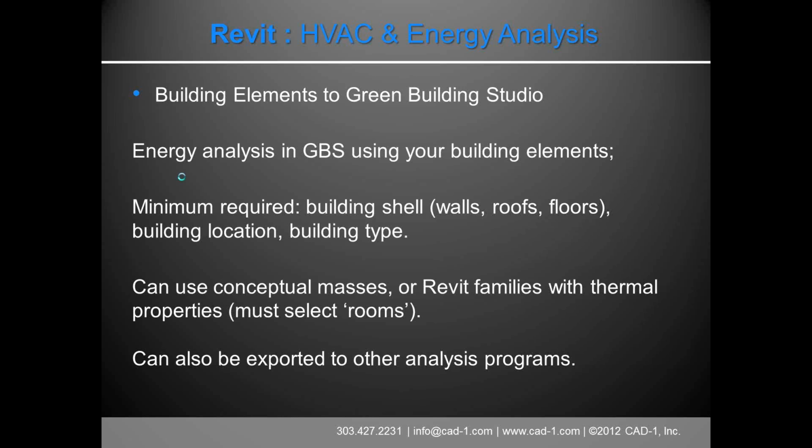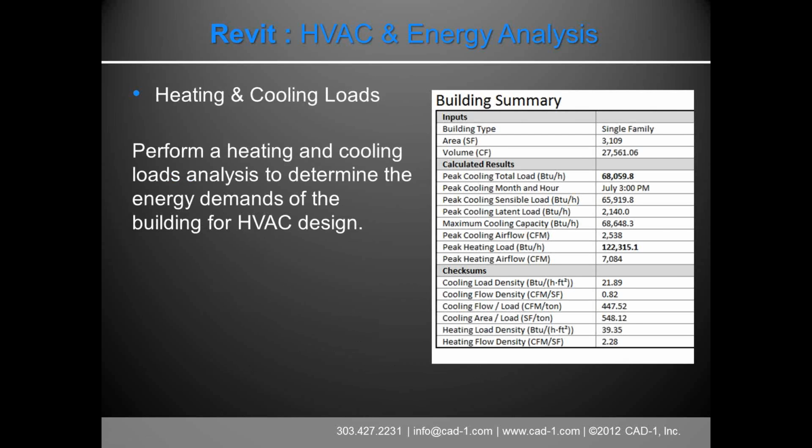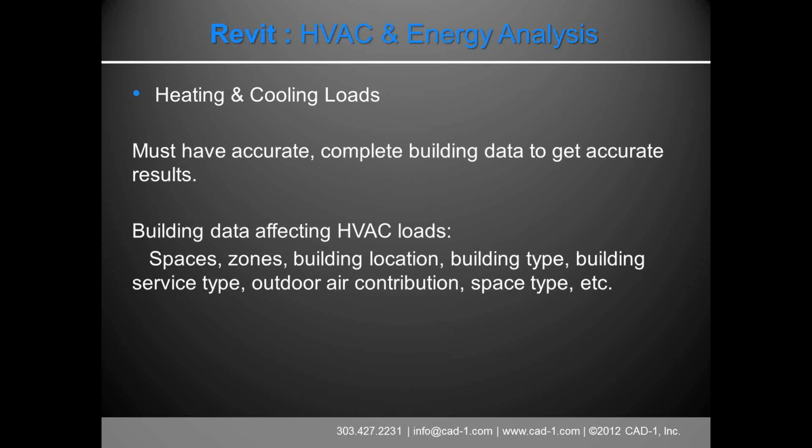So the third type is the heating and cooling loads. Within this one, we can perform a heating and cooling loads analysis to determine the energy demands of the building. I'm going to go into a little more detail on this one. Maybe the most important thing to remember is if you put good information into it, you'll get good information out of it. If it's poor assumptions going in, you're going to get poor accuracy coming out. You really need to have an accurate, complete building model with accurate data to get accurate results.